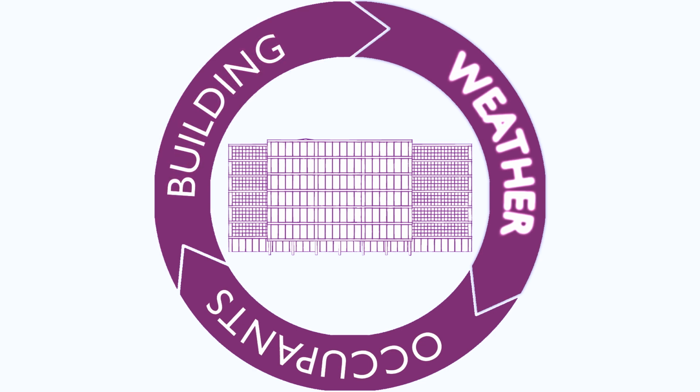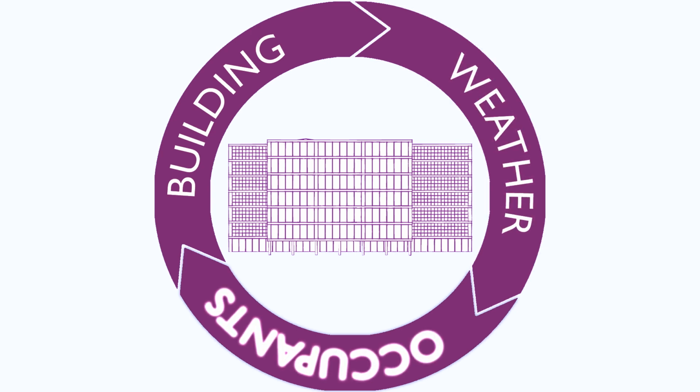Construction moisture can also come from the weather, and this must also be taken into account along with the weather conditions the building will be subjected to once completed. Being weather-tight earlier in the construction process and generally being composed of drier materials, off-site construction has an important advantage hydrothermally. By reducing the initial moisture loading on the building fabric, the design can be more precisely tailored to manage moisture associated with the occupants of the building and the uses the building will be put to, leading in turn to a more efficient fabric envelope and building system.